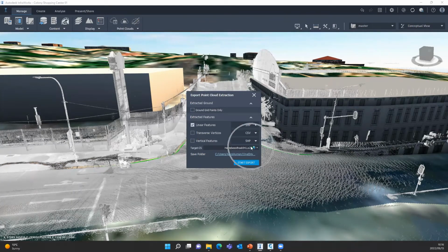You can also apply a coordinate system to this. So as you can see here, I have applied the Autodesk LO29 coordinate system to it. I've went and verified the coordinate system. I've created the model in the same coordinate system and then imported the point cloud. Now, before I move over to Civil 3D itself to show you what that looks like, I've already created the shapefile. I've simply exported it.